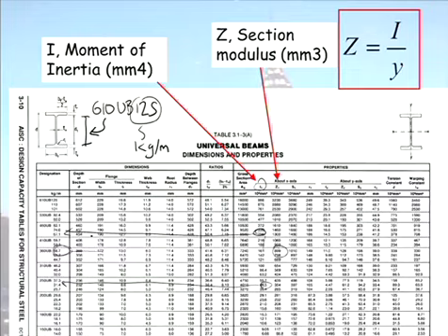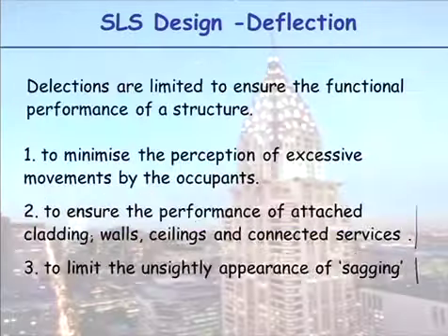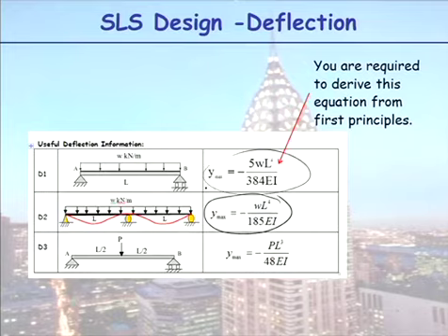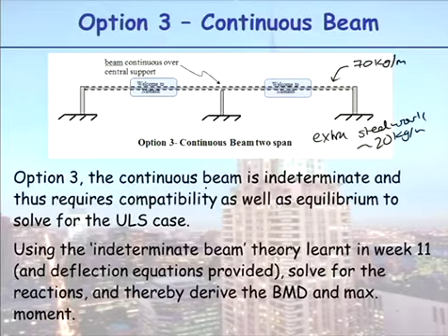The bigger of the two, yep. And in the brief it says which is the critical load case. The critical load case is the one that dictates how big it has to be. So it's the one that's the bigger one. Okay, so you do this, I said simply supported beam, you're given the deflection information. This is too hard for you to work out yourself, so you're given the maximum deflection. This term here you have to derive from first principles yourself, not hard.